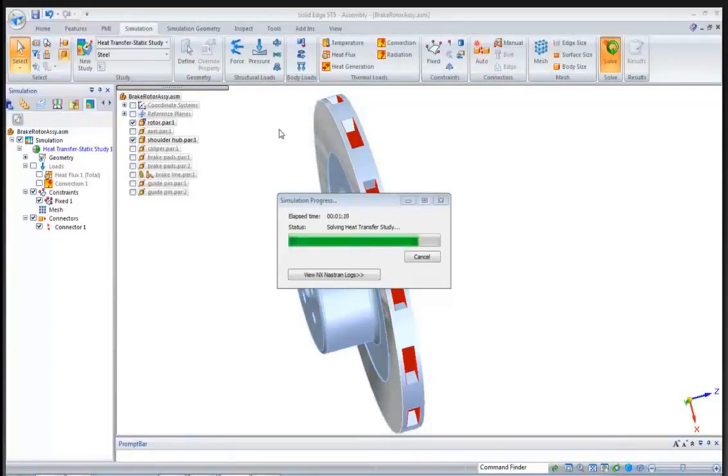And you can find that it's a given value for any material. So you can use the internet, use whatever your sources are that you normally use to get material properties, and enter that conduction coefficient. Now with convection, let's say I've got this surface here that's heating up,